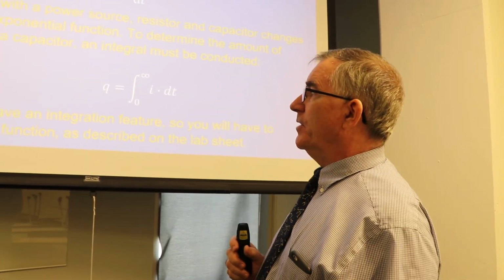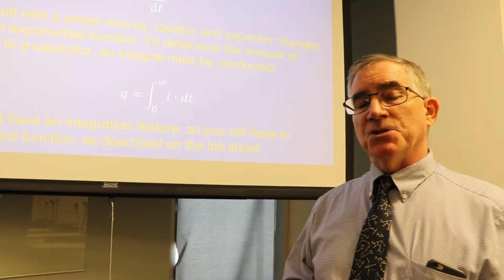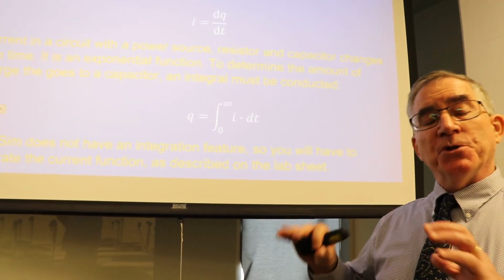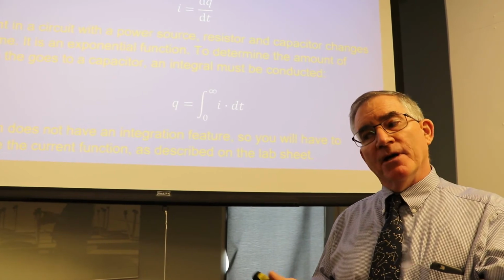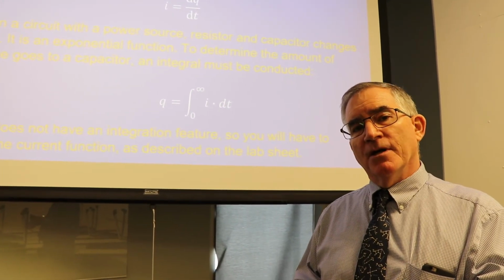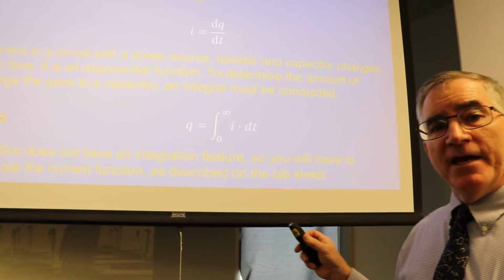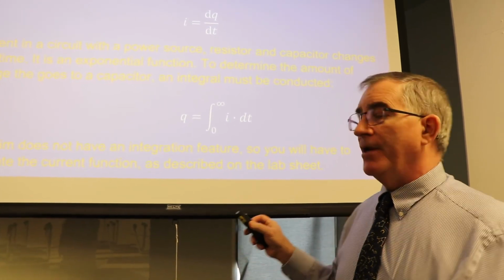Okay? So you're going to be doing that calculation for all of the capacitors in the circuit, as well as treating the circuit as a whole capacitor called the equivalent capacitor, and then you're going to be measuring the charge on that equivalent capacitor for 10 different voltages. All right, and you're going to do all that in MultiSim. And in fact, this is your first MultiSim experiment.